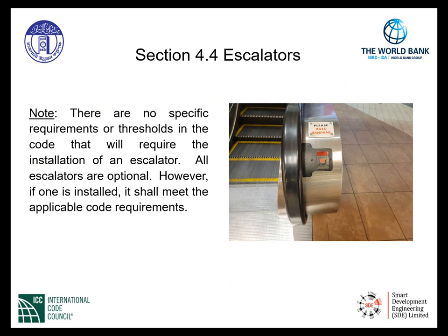A note to the code user: there are no specific requirements or thresholds in the code that will require the installation of an escalator. All escalators are optional. However, if one is installed, it shall meet the applicable code requirements. Unlike lifts, there are no specific requirements that will require the installation of escalators. And again, if one is proposed to be installed, then it needs to meet the requirements, as well as all of the approvals needed by the authority and certifications.